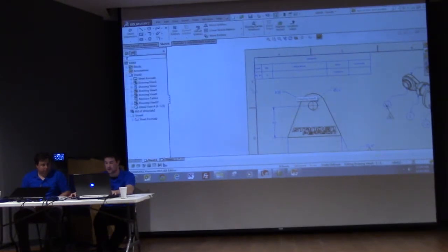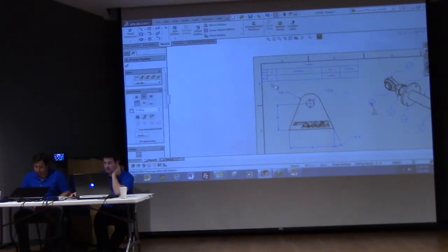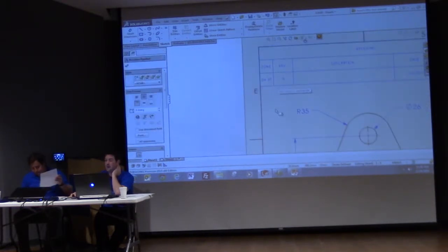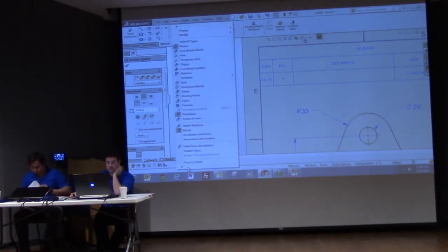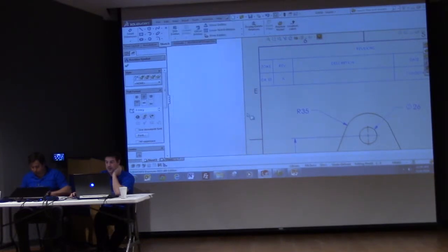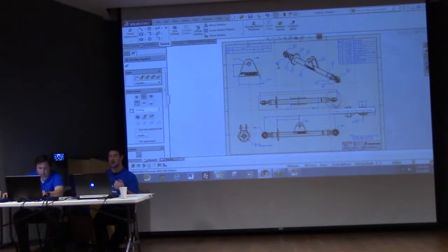Those are automatically inserted based on the zone lines that are now set in the sheet format. And of course if we move this up to say E5, you see that this automatically updates to be E5. Down here, you can see the zone lines now show the different zones on my drawing. Again, this is controlled in the sheet format, and it allows us to use these zones for notes and any annotations that we're creating.